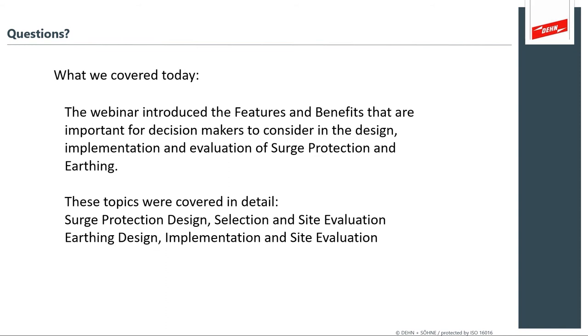Yes, Mark, I would just like to add that you select a certain lightning protection level in your risk assessment, and that guides you to what SPD you need to select. You'll notice when you do the risk assessment that if you select a more stringent lightning protection level, say LPL 3, 2, or 1, which is higher than LPL 4, the risk keeps on reducing even though you've just implemented the same surge protection measure.